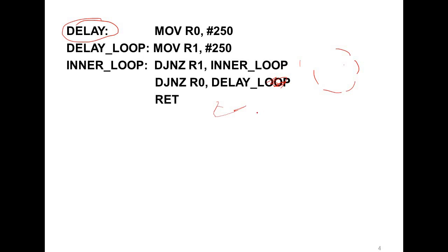Our main work is to send data to the motor so that the motor rotates, that is, it rotates stepwise. And after we send, the processor can't be idle. So in 8086 we will be using NOP, no operation. Okay, that is also an instruction. So we will be writing continuously.